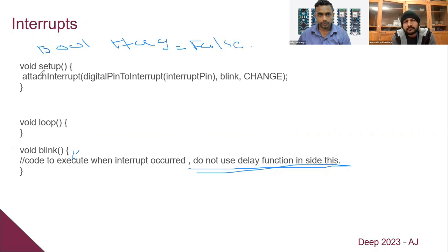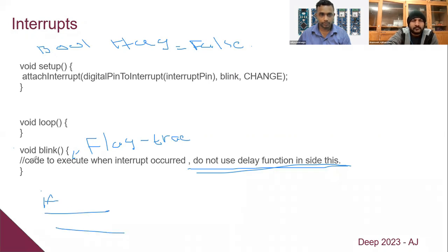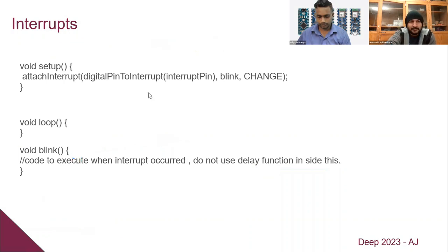When this interrupt happens, we register this flag as true. Then somewhere else we check if this flag is set, and do this. Like a state machine, we only use this to check the state and set a variable, so the processor won't hold at unnecessary points.